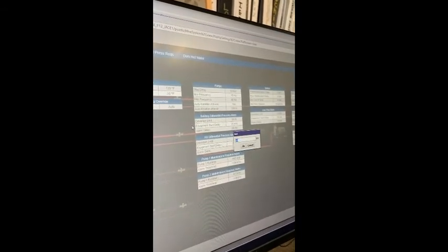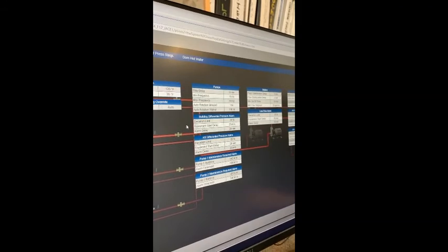I understand what a set is, sorry. So a set, in the code, would be like the starting point for that value. With an override, something else is writing into that point that we're displaying. But a set would be just a value going in, like a temperature set point, where nothing else is changing that in the code, and you just want to change it from 70 to 72. Like this pump stop delay, nothing in the code dynamically changes that. It's just a setting value.